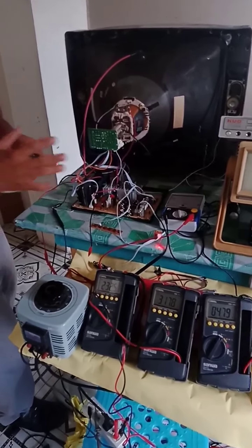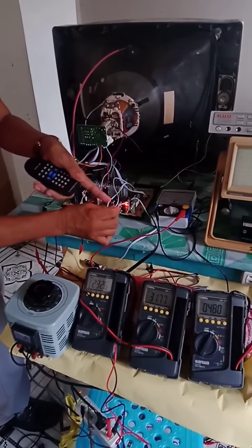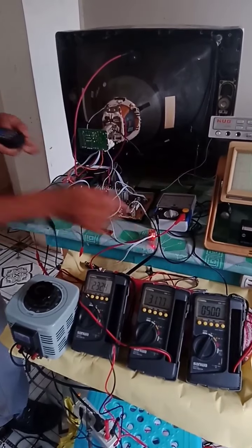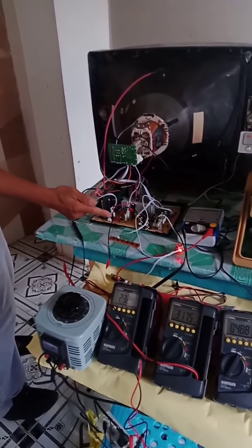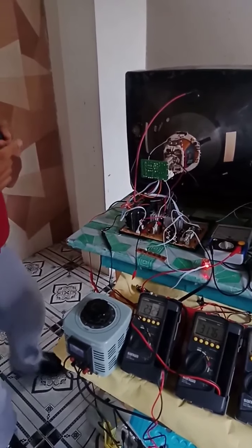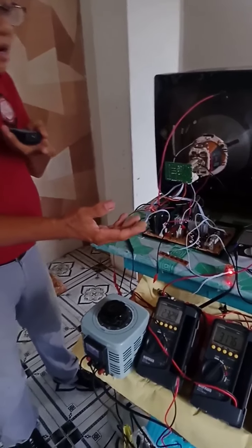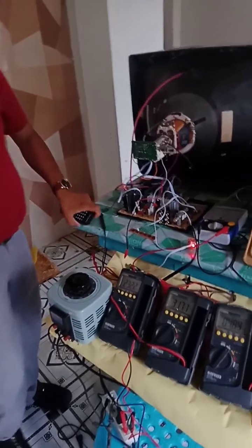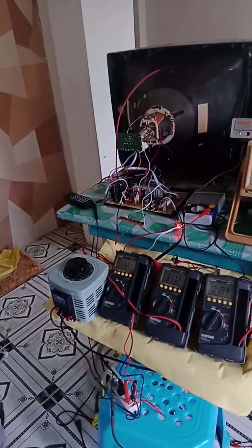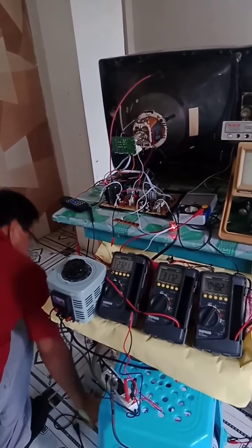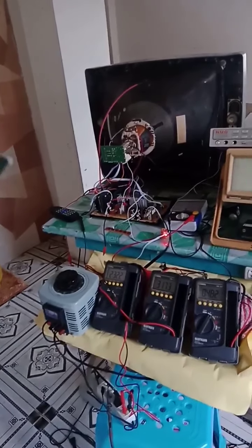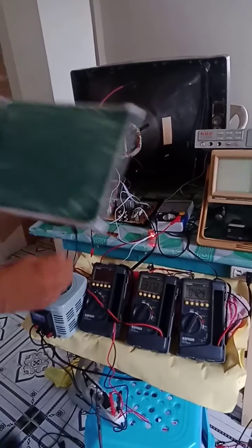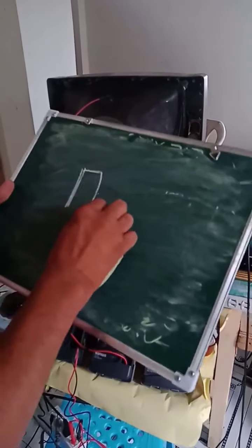Infrared transmitter or remote control. Then we have here an infrared detector, an infrared receiver that detects or receives the pulses being transmitted. The pulses actually are the binary information, being carried by 38 kHz. So this 38 kHz, by the way, class, is a carrier. We have here a series of pulses.